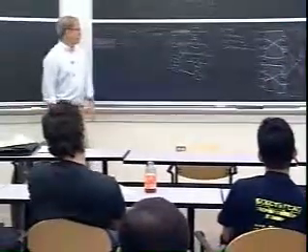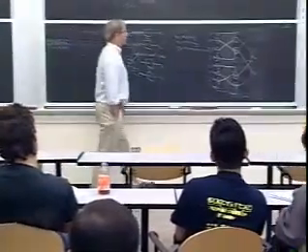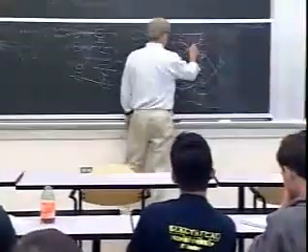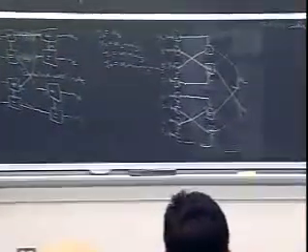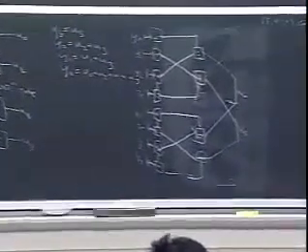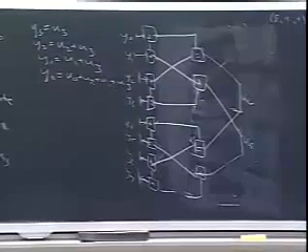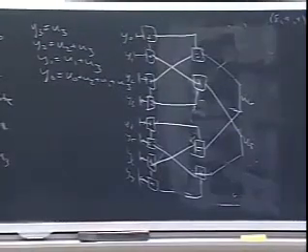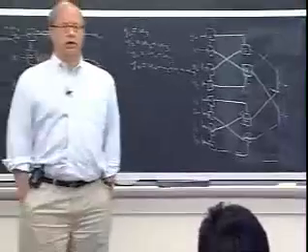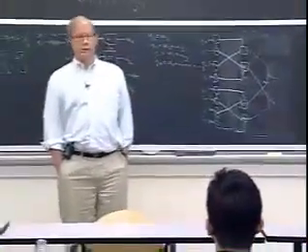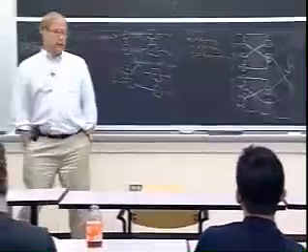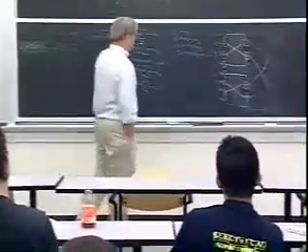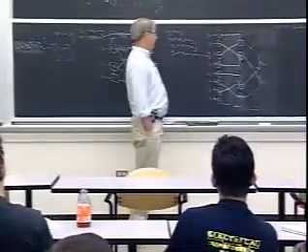On the other hand, it does have cycles, like this cycle here. When we get to the sum product algorithm, we'll see that there's a fundamental difference between decoding on a graph with cycles and a graph without cycles. Without cycles, we get an exact decoding algorithm that does maximum likelihood decoding, like the Viterbi algorithm, or actually a posteriori probability decoding.